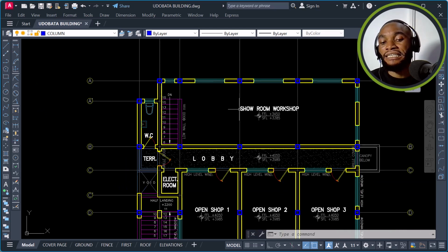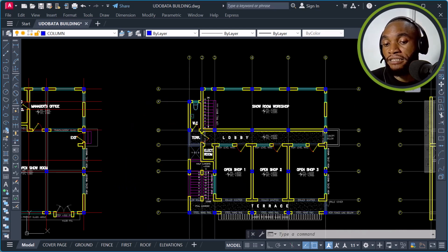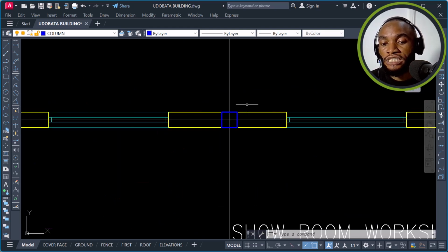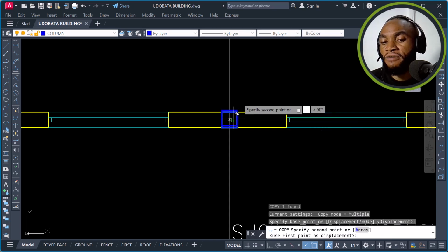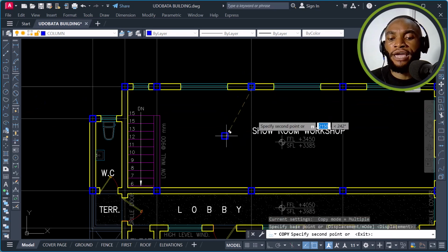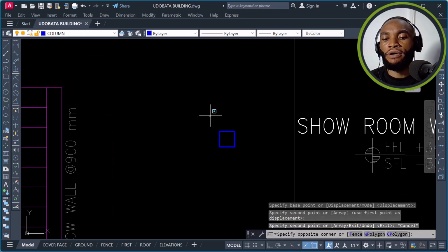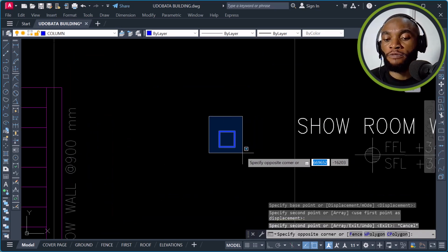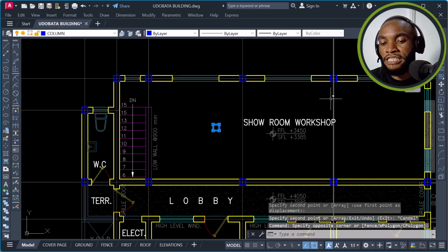Basically, this is a simple structural building plan for everyone to start with, okay? But there are some complex structural building plans where, by the time you superimpose, you will see that a column that appeared well on the ground floor is appearing on empty space on the first floor, indirectly causing obstruction to people using this first floor.